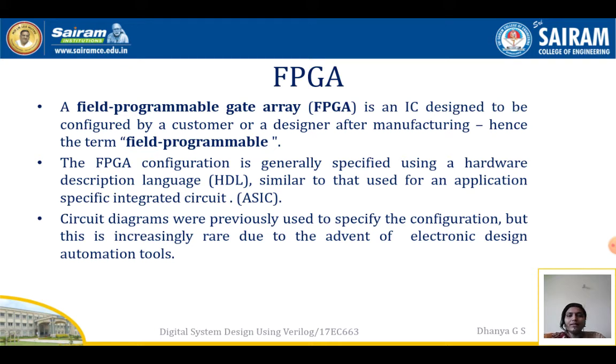It is an IC designed to be configured by a customer or a designer after manufacturing. Hence the term field programmable, because it will be done by the customer or the designer after the manufacturing. The FPGA configuration is generally specified using a hardware description language, similar to that used for an application specific integrated circuit. Circuit diagrams were previously used to specify the configuration, but this is increasingly rare due to the advent of electronic design automation tools.